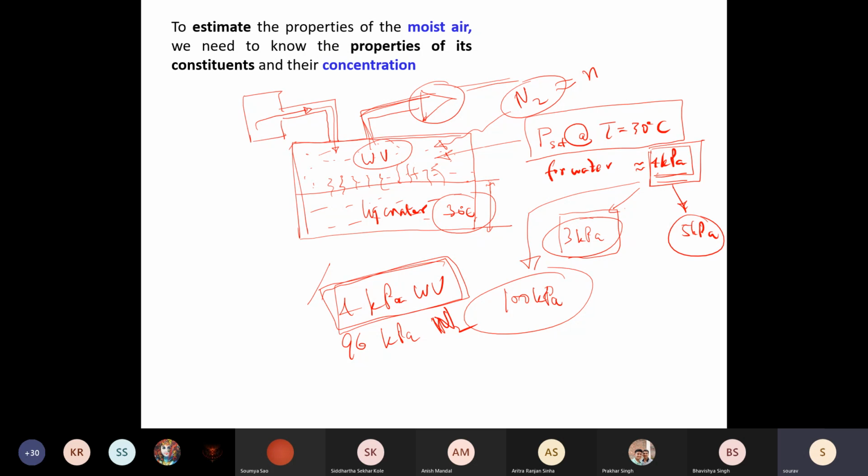When you reach a particular low pressure, only then do you start to see a lot of vapor bubbles coming out from the entire liquid column. That vigorous phenomenon will happen only when the pressure above it is reduced to a certain value. Till then, you will just see that the entire system is steady and air is being continuously drawn out by the vacuum pump.